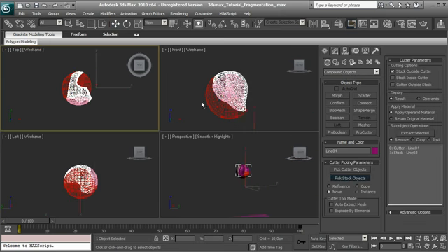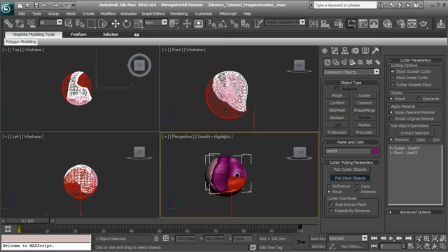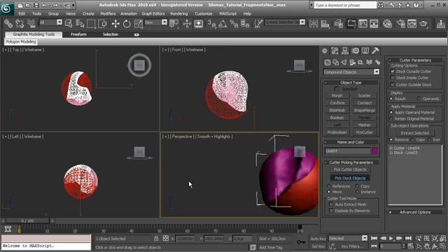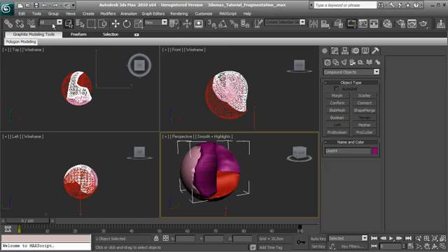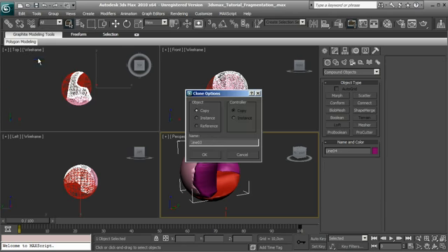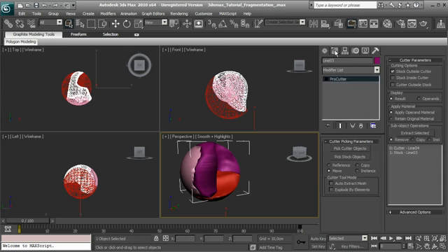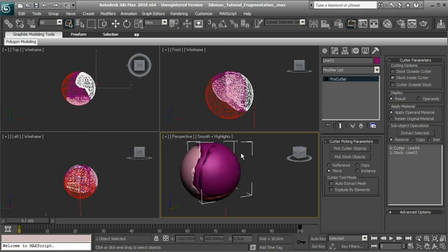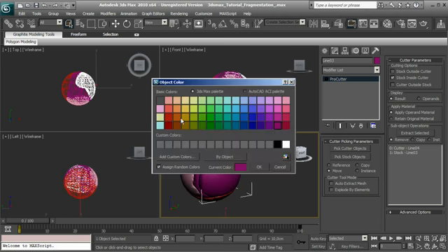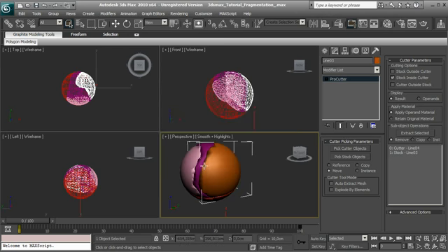and I select this one, and you can see that we have split the mesh again, and I select Pick, I go in the select mode, edit, clone, copy, and I select stock outside and select stock inside, so we have another piece of the mesh.